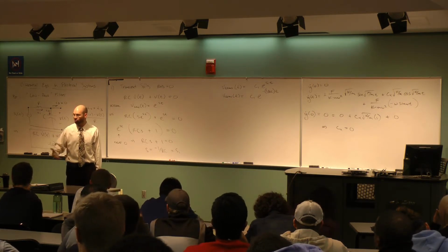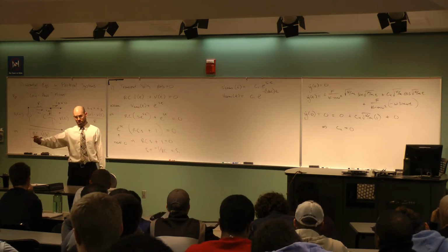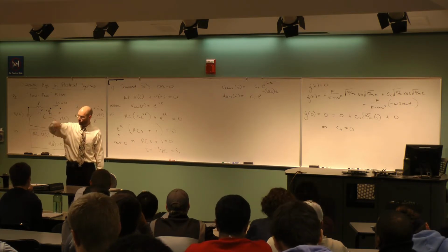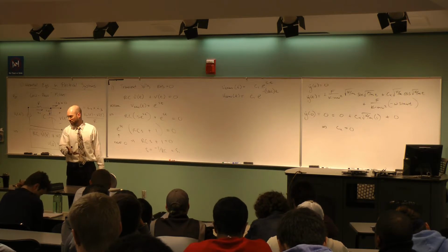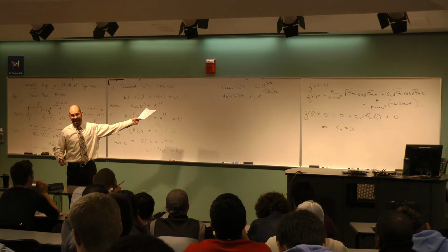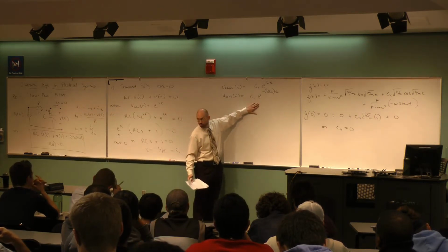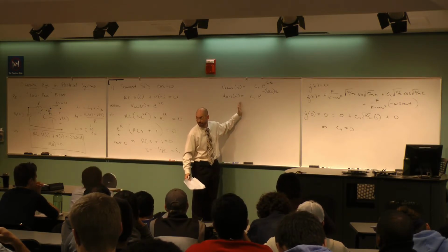The transient solution is always exponential. If it's an imaginary number, an imaginary exponential is really sines and cosines. It oscillates. If it's not an imaginary number, like this, 1 over RC, okay, then it means it's a decaying exponential, which means as time gets large, what's this equal to? 0, which is why we call it the transient solution.